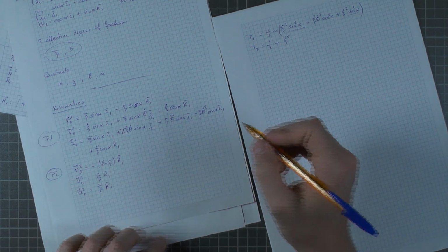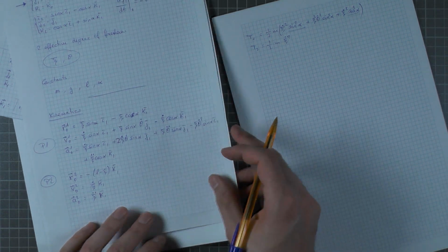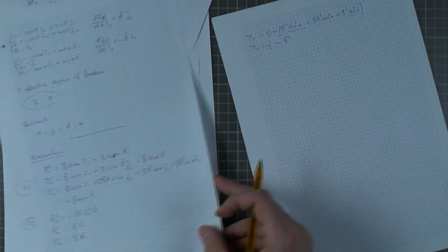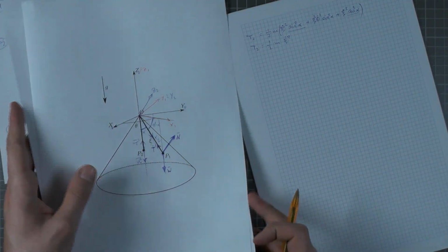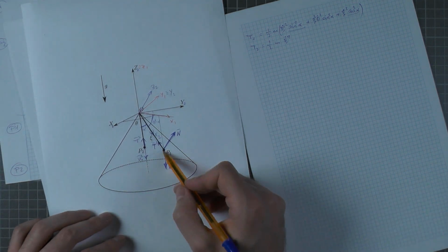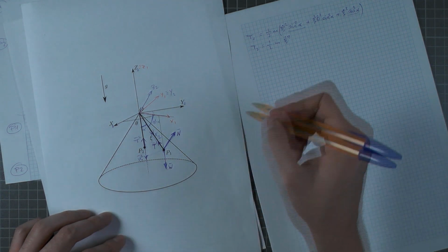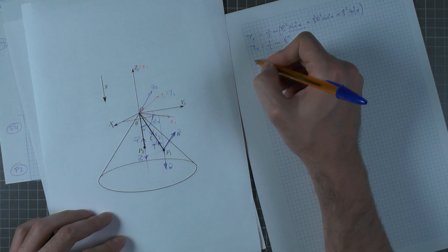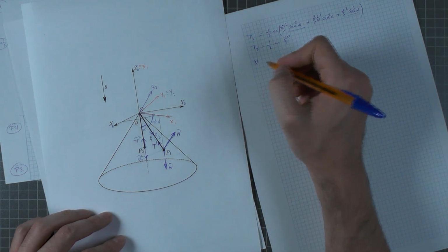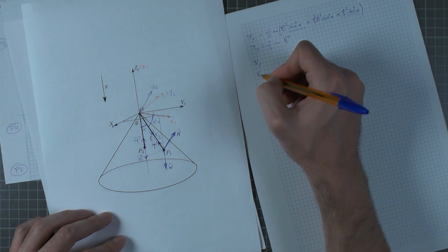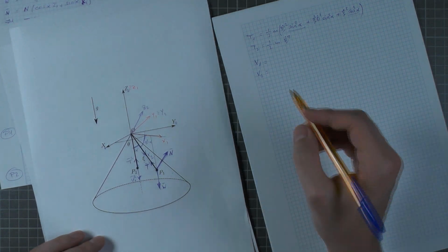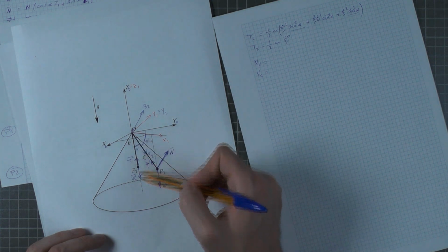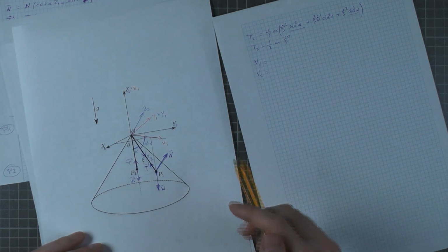Now, regarding the potential energy of the system, we only have to consider the weight on each of the particles. So we need to write down the potential associated to the weight of particle 1 and particle 2. Let's start with particle 2. What we want is to multiply mg by the height of the particle along the vertical direction.